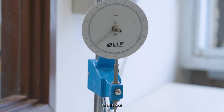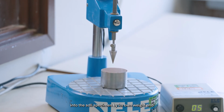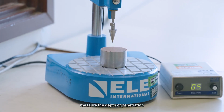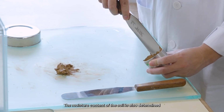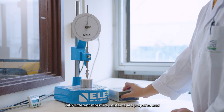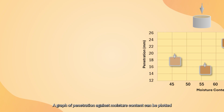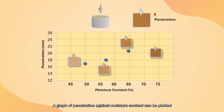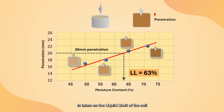In this test, we let an 80-gram stainless steel cone penetrate into the soil specimen by its own weight and measure the depth of penetration. The moisture content of the soil is also determined. At least 3 more specimens with different moisture contents are prepared, and the penetration test we have just described is then repeated. A graph of penetration against moisture content can be plotted. The moisture content corresponding to the penetration of 20 mm is taken as the liquid limit of the soil.